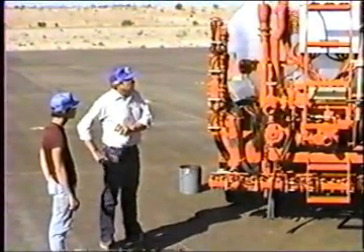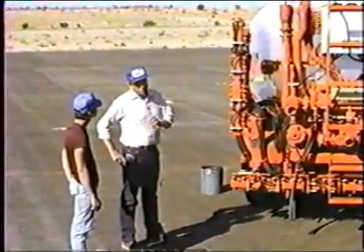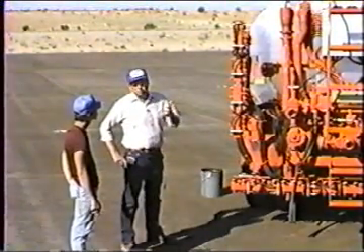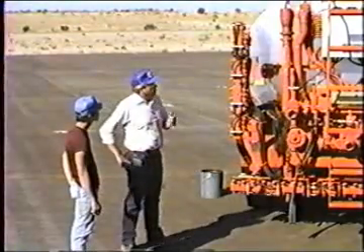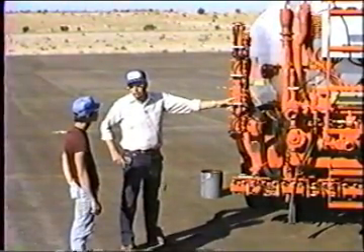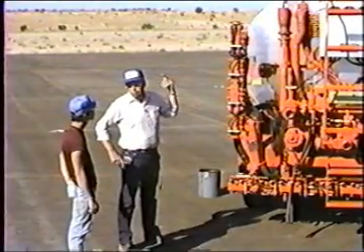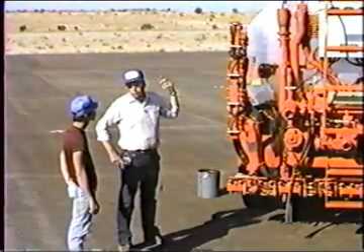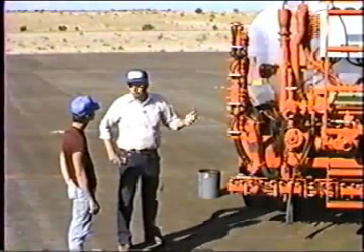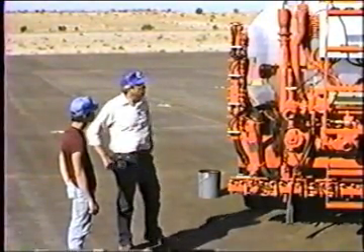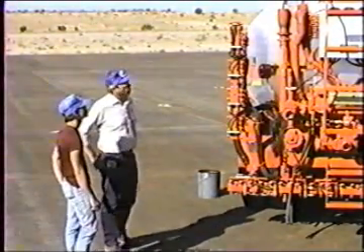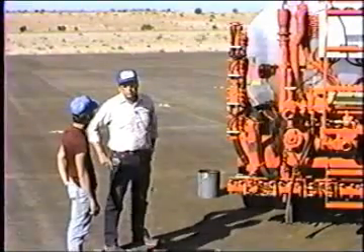Very common for an asphalt distributor to not put down the same rate all the way across. Maybe they've asked for 1/4 a gallon to the yard, and very possibly the right hand side of the bar is putting down 5/10 of a gallon to the yard, and the left hand side is putting down 1/10 of a gallon to the square yard. Maybe the average is coming out to 1/4 of a gallon, but nowhere is it actually just right. The equalizer system is very important. There's a few places in the country, a few places in the world, that actually test the machines for that.